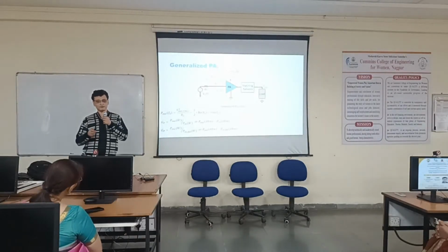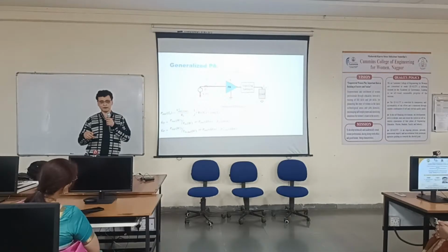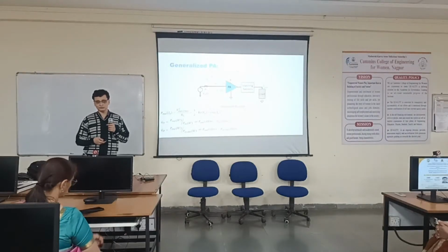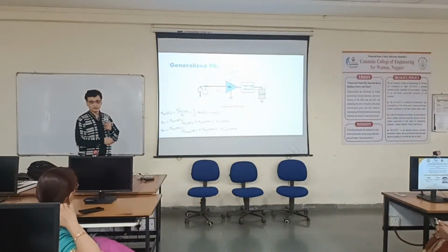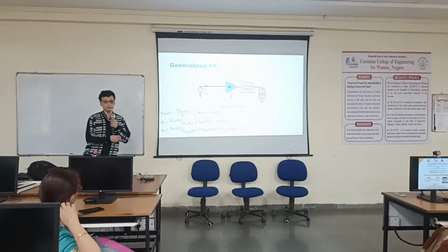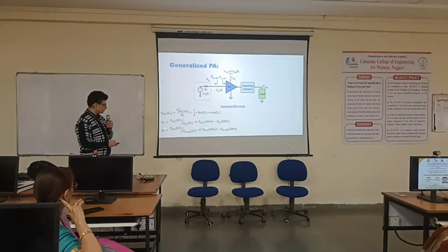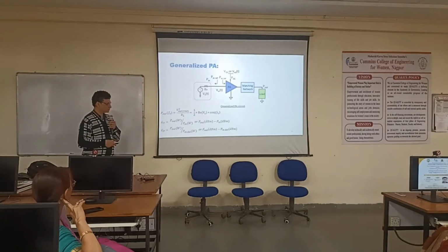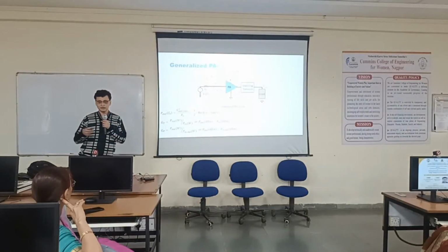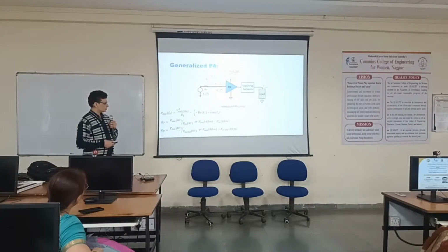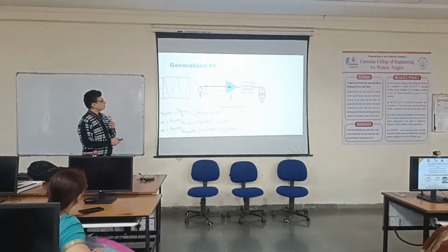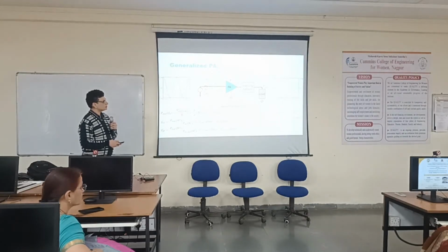But what if the total power input into the power amplifier is not 10 watts, but say lesser than 10 watts? Then what is the gain? Based on that, GT is the one that I just described: the output power divided by the total power the input source is capable of delivering. But you can also define the power gain as the power delivered to the load divided by the power that is actually entering the amplifier. So these are the definitions of GP and GT.